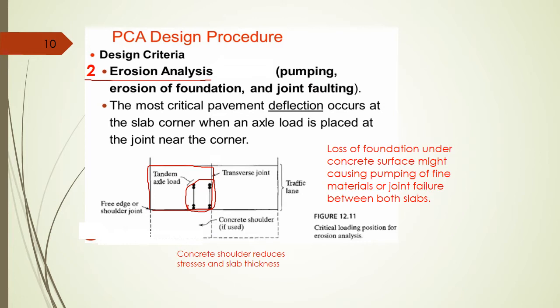It's very important to know when you use concrete shoulder. The concrete shoulder reduces stresses and slab thickness. The erosion analysis is very important because we need to limit the loss of foundation under concrete surface, which might cause pumping of fine materials or joint failure between both slabs.